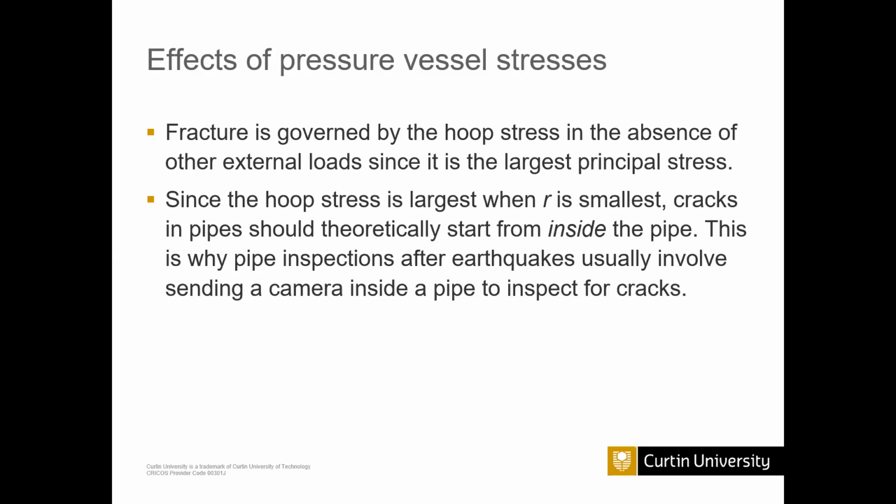They will do the inspection of the inner surface after any earthquake or after anything happens. They will check the stress at the inner surface, because in this whole case the tangential stress is maximum at the inner surface.